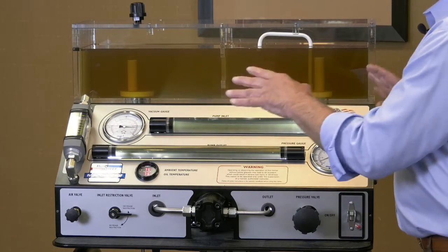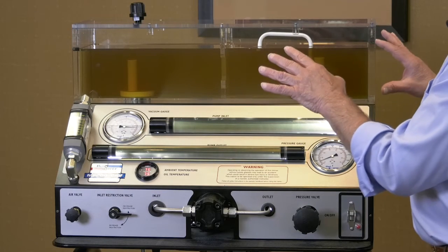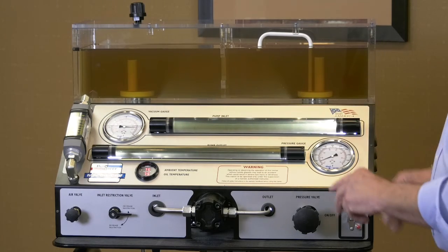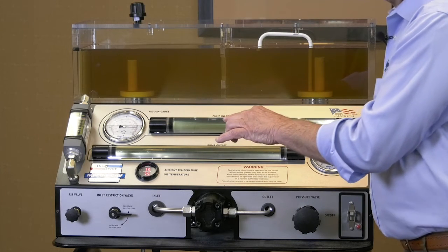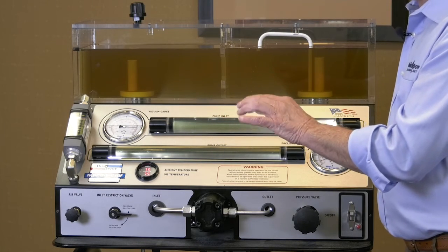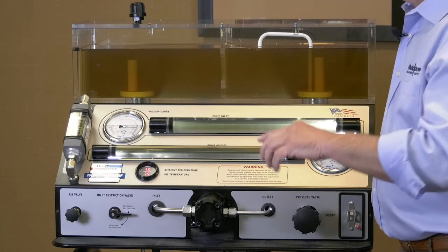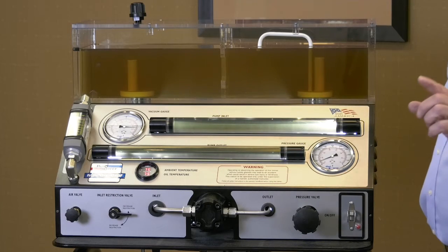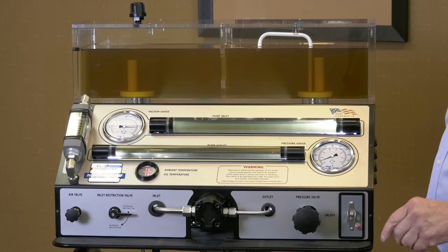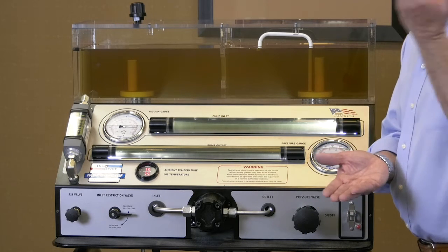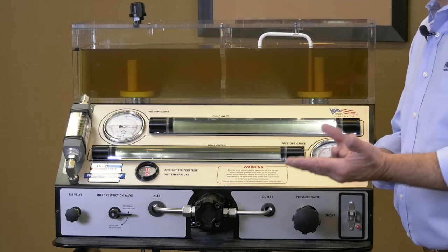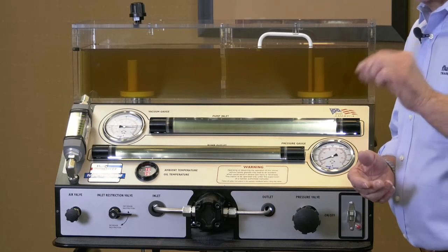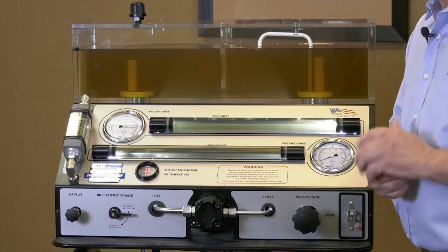So as long as this hydraulic system is operating at 1.8 GPM, at 75 degrees ambient and 75 degrees oil temperature, at this altitude, that number should never change. Any increase or decrease in that 5 inches of mercury would be indicative of a problem in the system, since my point of reference is 5 inches of mercury.